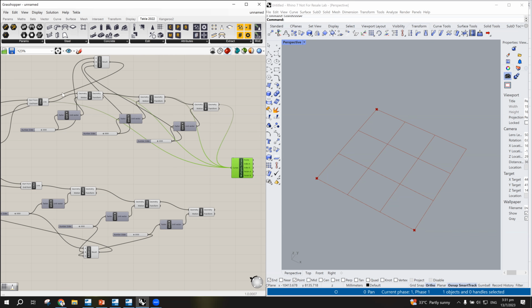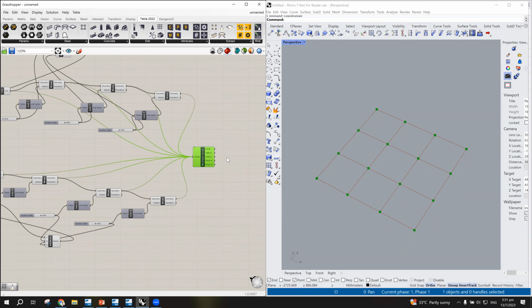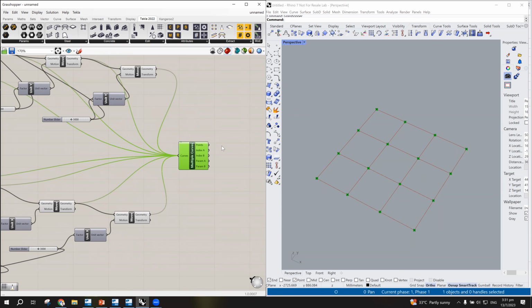So you need to press the shift key to link everything here. I already linked the above geometry. Now the bottom one, shift key. Look, it will add these points. See here, it will add these points here again, and this one. So now I already have all those points. Are we clear on this?